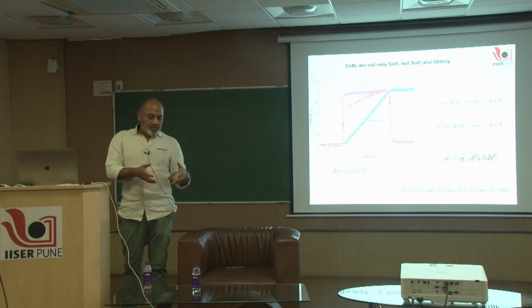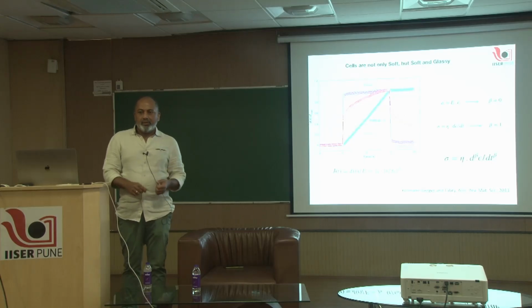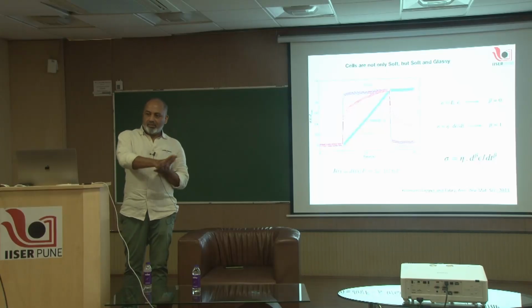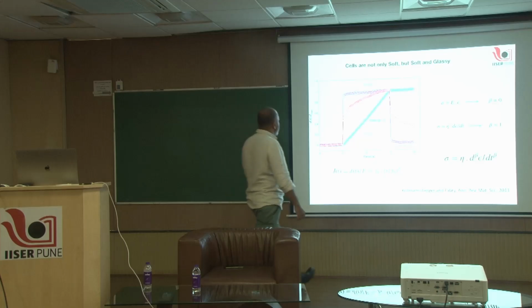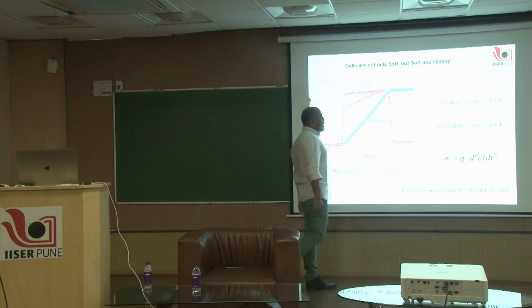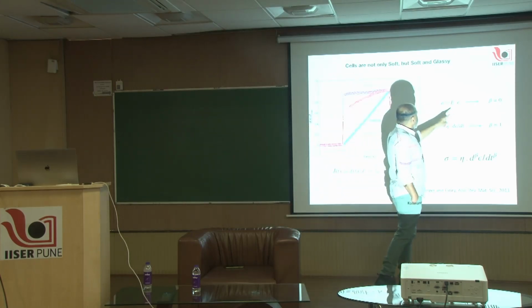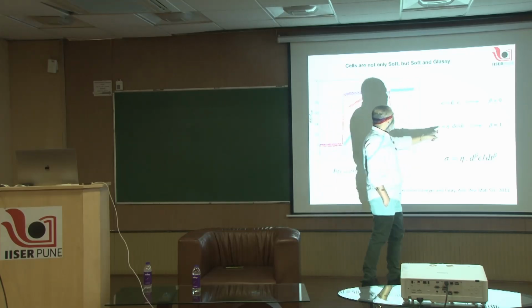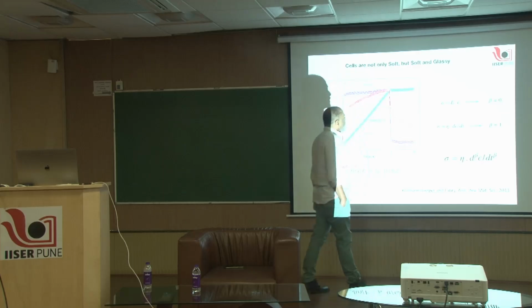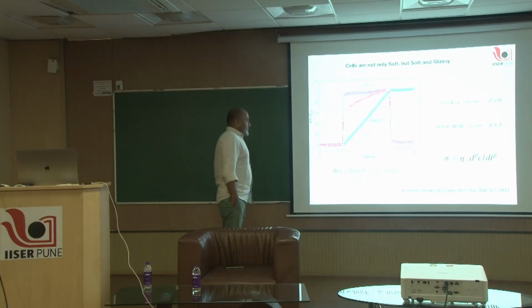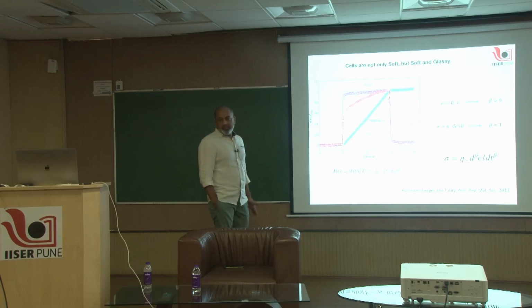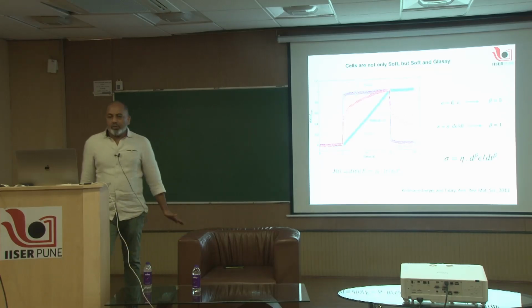So for instance, if I take something like clay and deform it, and I take back the force, the clay doesn't come back; it remains the way it was. This is what I mean by whatever deformation is produced, it basically continues. These two follow constitutive equations: for solids, stress over strain is the Young's modulus, and for liquids, the stress and strain rate are related by eta, the viscosity, the proportionality constant. Okay, so that's for the two extremes.